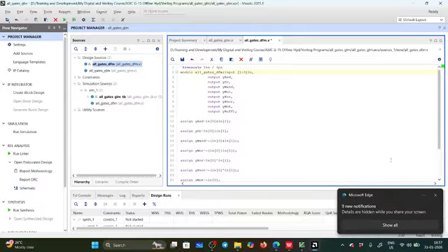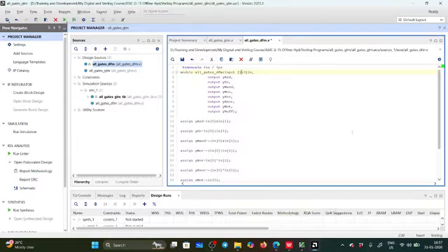There you need to use the parameter concept, so we'll discuss it in the future. The parameter concept we need to use when you want to reuse. Suppose a ripple carry adder has a fixed size of 4, and the client asks for 8 bits or 16 bits. During this code we can't change that.